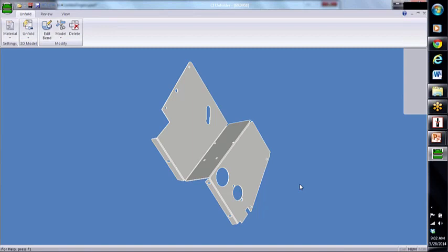The other thing is, in that process, a CAD operator or somebody who is going to generate the Cincinnati part file has just as much opportunity of bending a flange the wrong direction as a press brake operator does. And if they bend it the wrong direction and send it to the floor, the press brake operator will follow suit and create the part graphically from that. And what they do is bend the part the wrong direction in the virtual world, grab their real material with their real press brake, bend the part and form it in the wrong direction in the real world, and you have real scrap, you have virtual scrap that turned into real scrap.